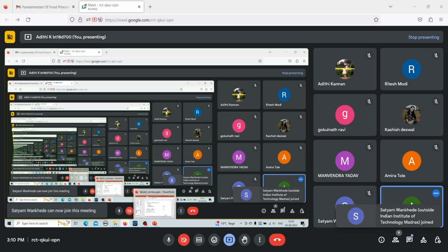Question 16. Relaxation time. This is something that we're discussing again, just in case you didn't understand previously. The relaxation time is observed when the stress reaches dash of the initial stress. So here I'm giving an instantaneous strain. Again, this is an example of a stress relaxation test. Strain is constant. So I'm giving a constant strain, and I'm measuring the stress relaxation, which comes out like this. You see that my stress slowly, gradually drops.